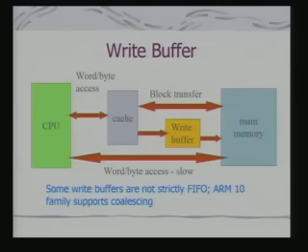In many architectures, these write buffers are not implemented as a queue, but in a different way. For example, the ARM10 family supports what is called coalescing. That means you can write the data and it is grouped together, and then the group or a block is transferred from the write buffer to the main memory.